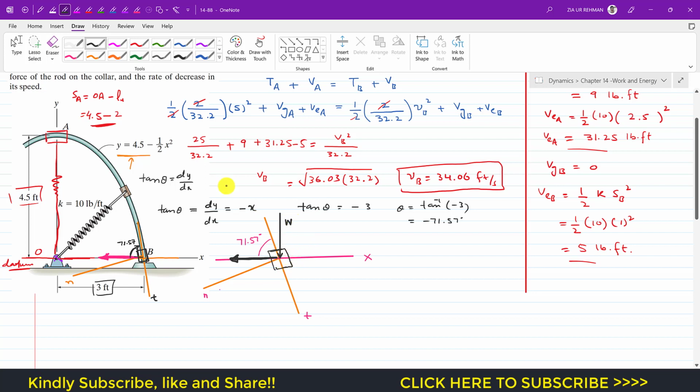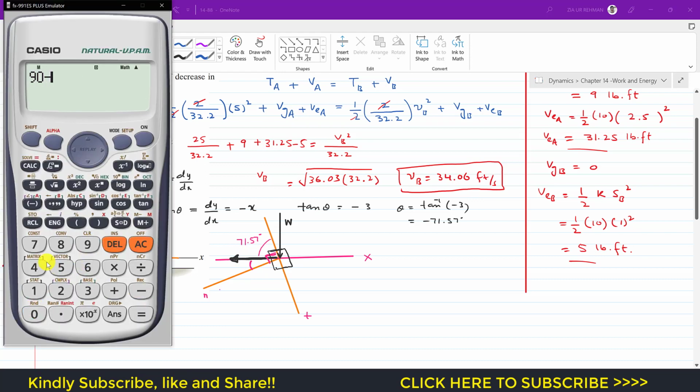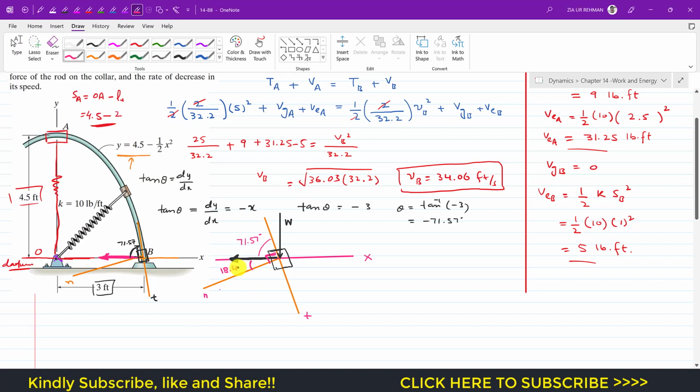And similarly, if the angle between the normal and the tangential axis is 90 degrees, then this angle is 90 minus 71.57, which is 18.43. So here we have an 18.43 degree angle. And similarly, the angle between the weight and the x-axis is 90 degrees. Since the weight is vertical, this angle is 90 degrees. So again the weight is making that same angle, 18.43 degrees here. So now we can resolve the weight and the spring force.